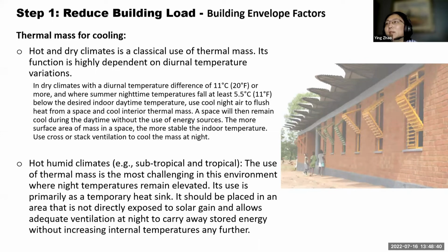So after the whole night, the thermal mass is cooled. In the morning, when the people come in, the space will then remain cool during the daytime without using any energy to cool the building. The more surface area or mass in the space, the more stable the indoor temperature will be.